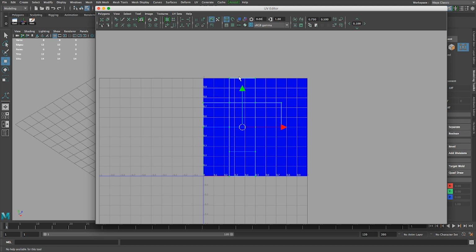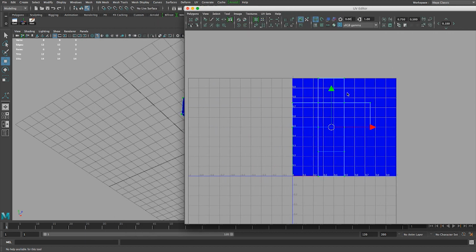What I could do, let's say if I said this is the only thing I need to UV, now I like it because it's all combined, but I could also say, you know what, this is the one that's blocking me. If I would scale all this up, this cross, and then I would stick the cube in between, I will use more of the space. So I can always, after we stitch them together, also select this edge. And you should have, again, this is the last command in this one, I think. Shift. The same as we have move and sew UVs, we have cut UVs. When I do cut UVs, I actually split this part. It stays in the same location, nothing changed, but I split it. We did exactly the opposite of what before we combined it, now we split it.